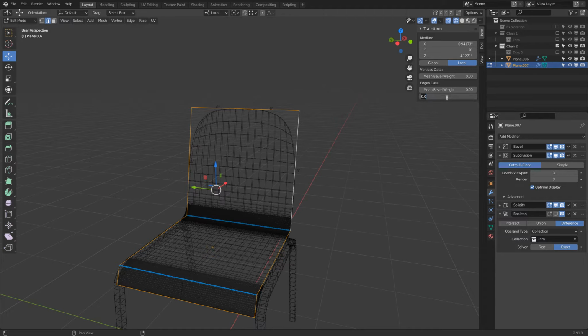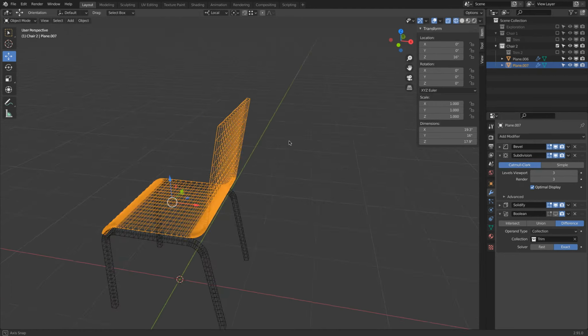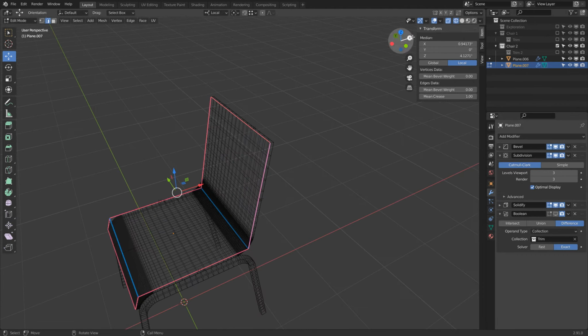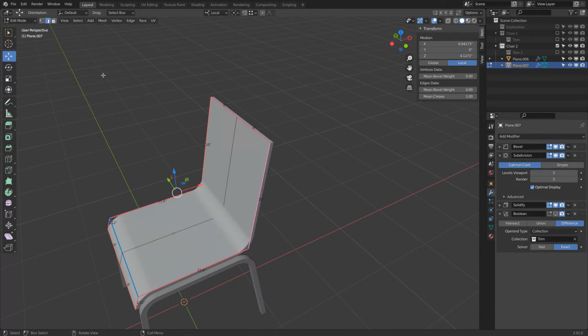Crease, like the name says, creasing: if you crease a folded piece of paper, you sharpen that edge. Here it's the same. Enter, and you see now it's tight right onto the edge. Very good. And now what we will do is move the corner points away, and then we will get a really nice soft representation.